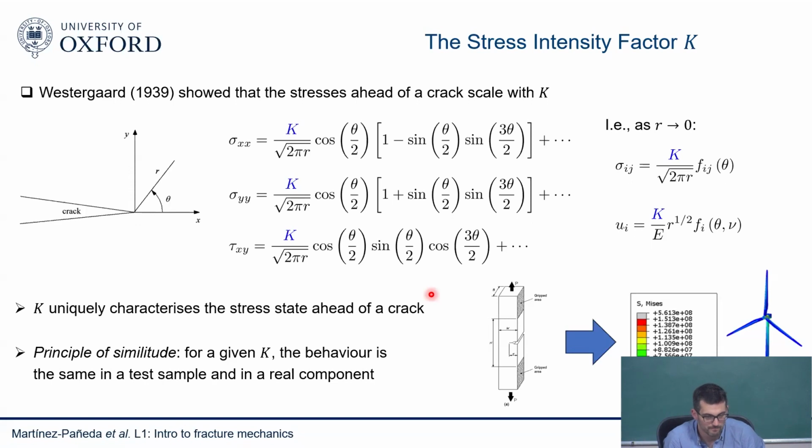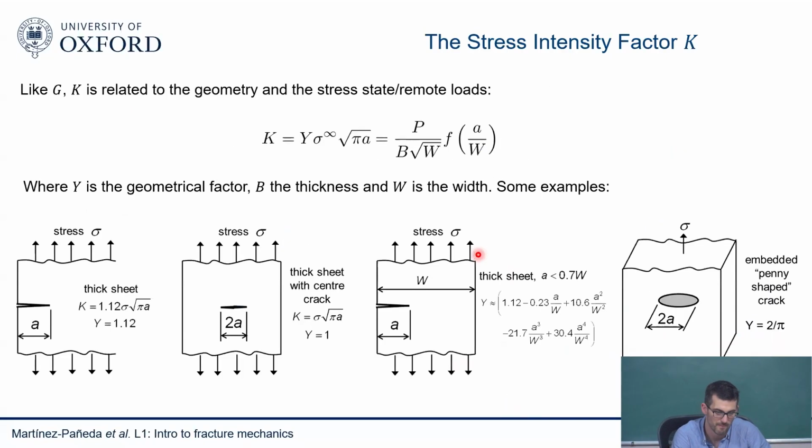So because there's a relationship between displacements and k, or stresses and k, we can do finite element simulations of any component. And engineers do stress analysis all the time, so you just need to add a crack now. Based on those stress fields or displacement fields, you calculate your stress intensity factor, and that tells you how likely that crack is going to grow. And you compare that to a critical stress intensity factor that you measure in your lab using a component where you know the relationship between the applied load and k.